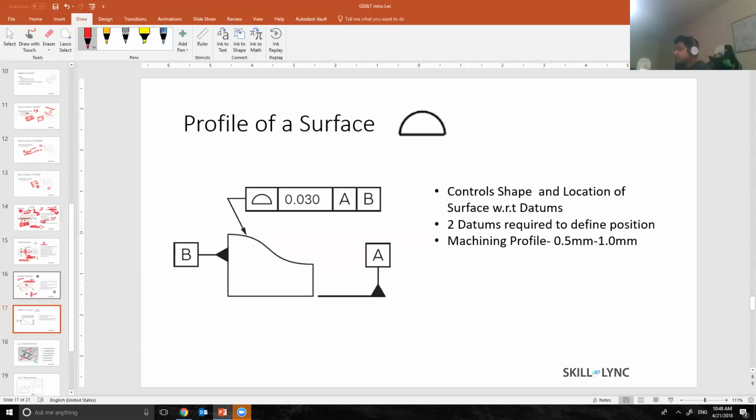So what profile means is that if I have a part that is fixed to my A and B datum, let's say in this case, I only want to constrain 5 degrees of freedom. That's why I don't have a tertiary datum. I don't have anything called out as C over here. Let's say I have some weird part and I just need to constrain A and B surfaces. It means that this part can come outside the screen.